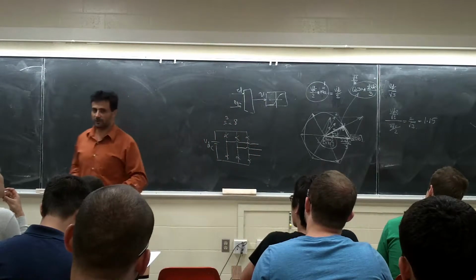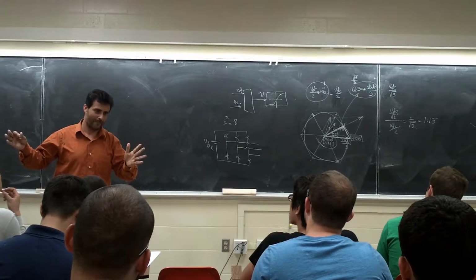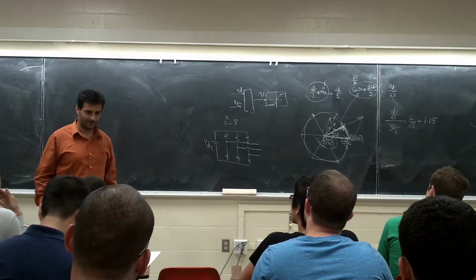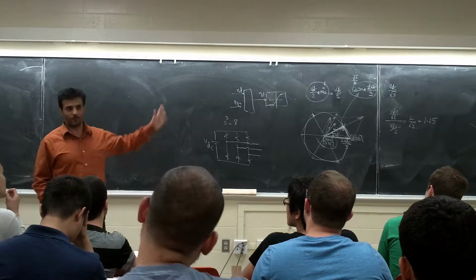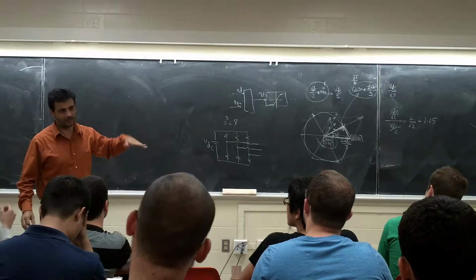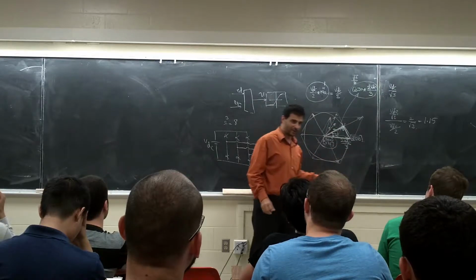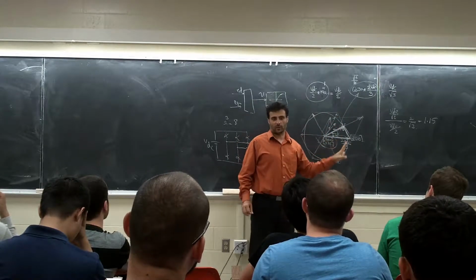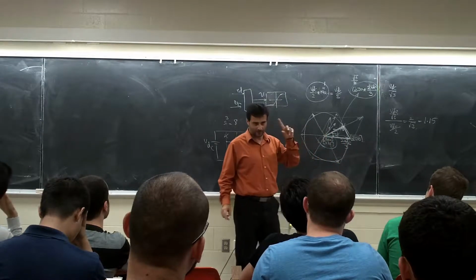You're going to get the same harmonic spectrum with maybe 40% less switching. You know what I'm saying? You get exactly the same thing with 40% less switching. These are a little bit advanced topics. I don't want to talk about it. But my point is, when we deal with the real space vector, you have the flexibility to select this.